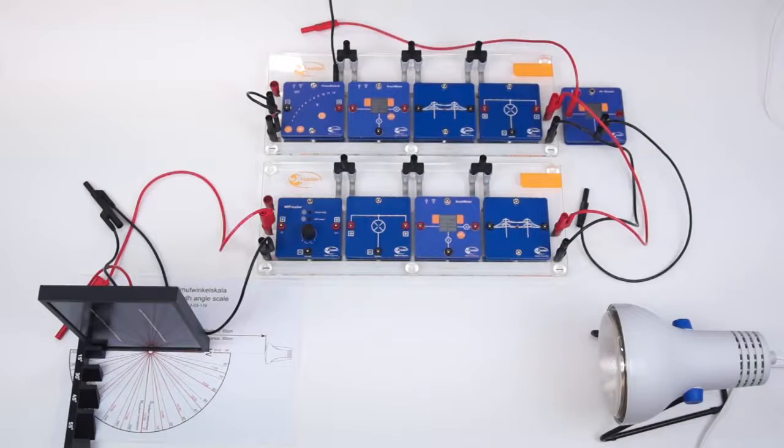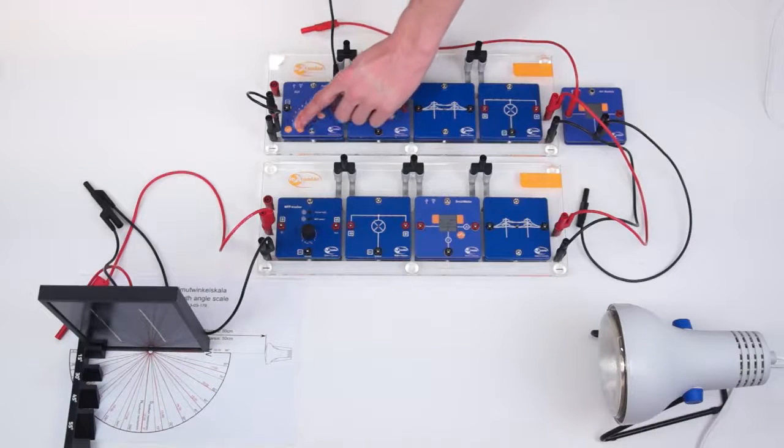To determine an overvoltage in a household in the experiment, we define for the experiment a nominal voltage of 3 volts, and like in reality, it is only allowed to differ by 10%. In a previous experiment with the same structure without the photovoltaic system, it has already been determined that the voltage values are best observed with a transformer voltage of 3.5 volts at both households.